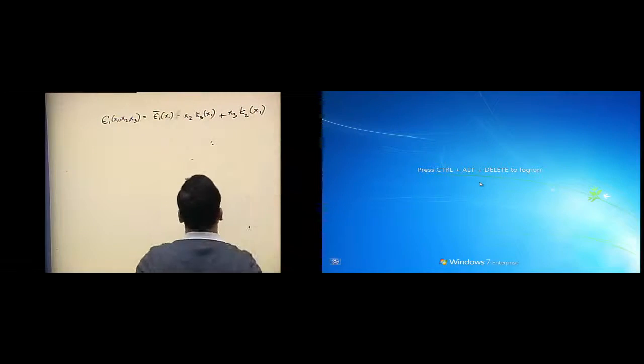K. Okay. So k3 is curvature, sometimes referred to as kappa or k, and then plus x3 kappa 2 x1. I think he covered till this point. So this essentially is an expression to evaluate strain at any given point in the beam. You just have to plug in the coordinates x1, x2, x3, and you will be able to evaluate the strain.